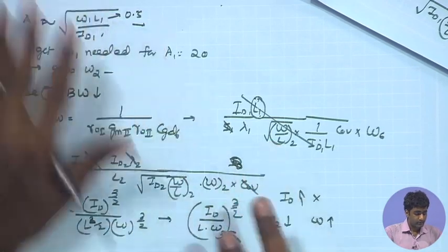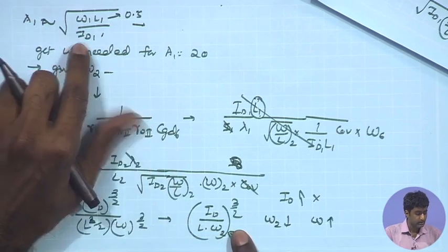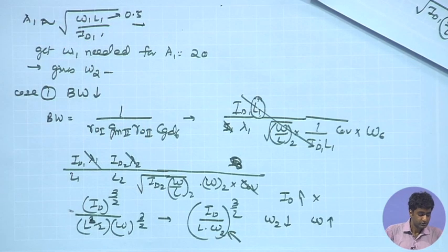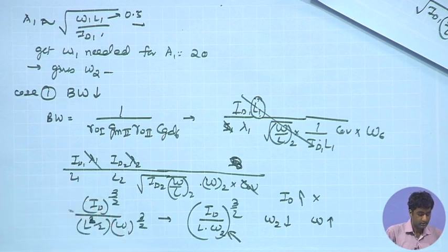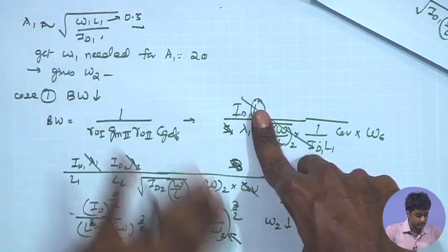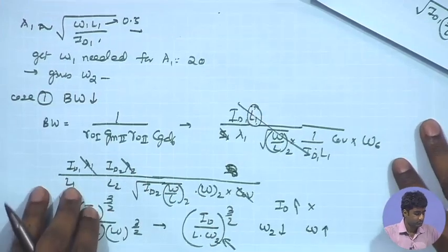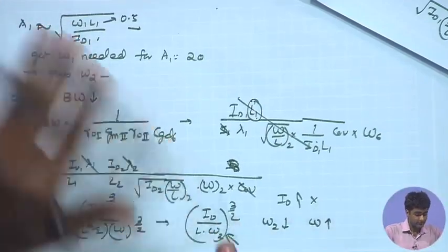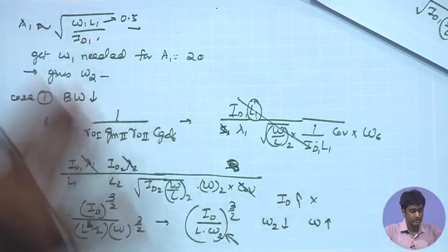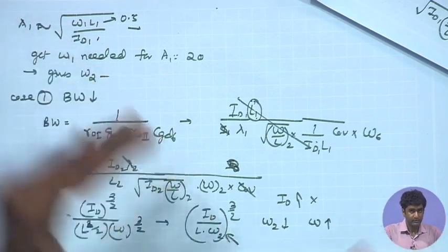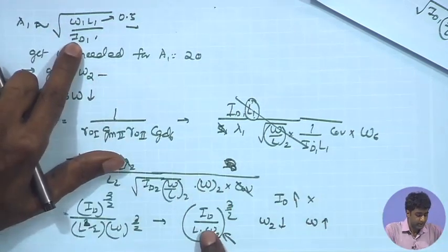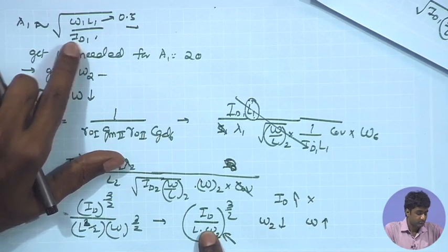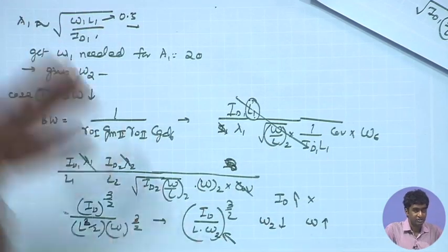Now if we are able to do that, another target would be that we would like to reduce the bias current also as much as possible, so that the gain and bandwidth both are maintained while achieving limited power consumption in the amplifier. So for that we can see once again these two operations. If you have to lower the power, suppose we have achieved this appropriate bifurcation between A1 and A2, so that the overall gain and bandwidth is now being met. Now another target is to check whether we can reduce ID further. So again these two equations are going to give me some direction regarding that.